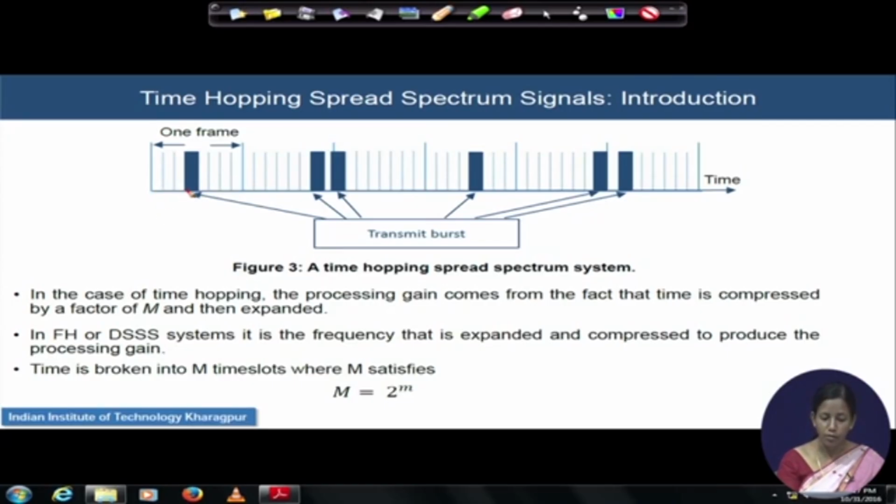And now the choice of which subframe you are transmitting this burst in is a question, and that will be selected by a PN sequence. So, the PN sequence will help you choose any one of the subframes randomly within a frame. The bits that are transmitted here are collected here, and the bits that are transmitted here are collected here. So, every frame is basically transmitting the accumulated bits of the earlier frame.